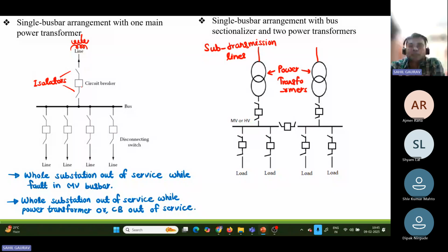So the length of primary feeders in low load or rural areas is restricted by voltage drop, while in high load density, industrial or commercial areas, the length is restricted by thermal limitation and capacity limit. Thermal limitation and capacity limit are the same thing.